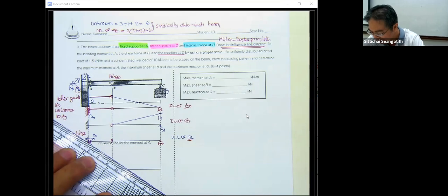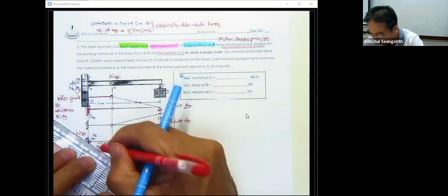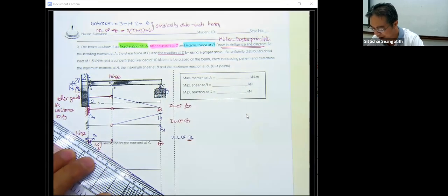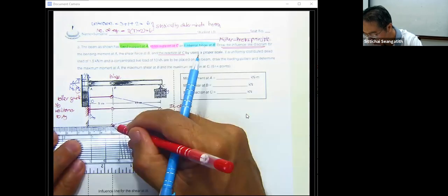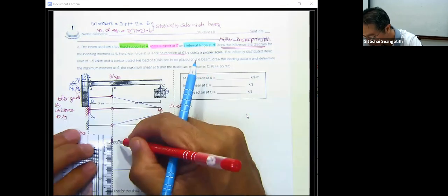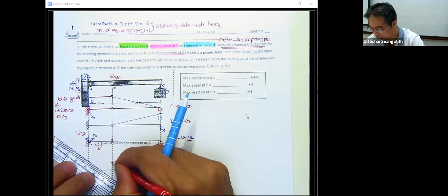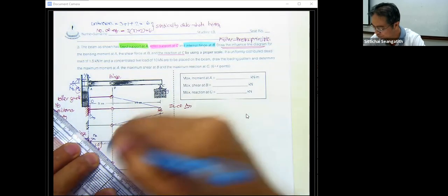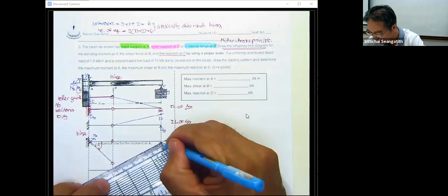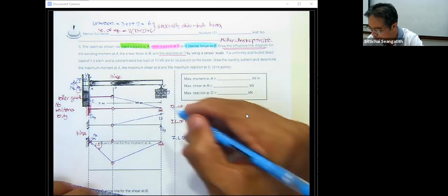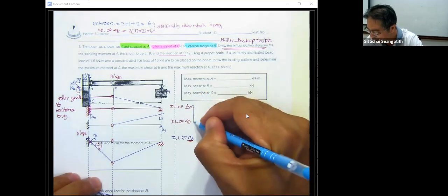When it rotates, the relative rotation is going to have a 1.0 slope. And then if this one is 5 meters and you measure it to be about 2.1 centimeters, this one is going to have 2.1 centimeters downward, to make it on scale. So we have the influence line of M sub A in this shape, which is part of the influence line for the reaction.